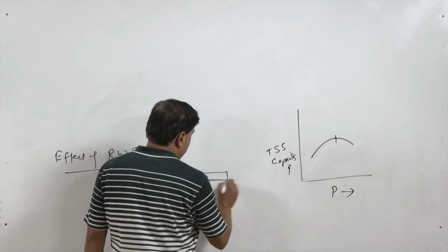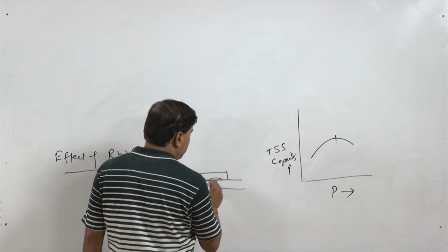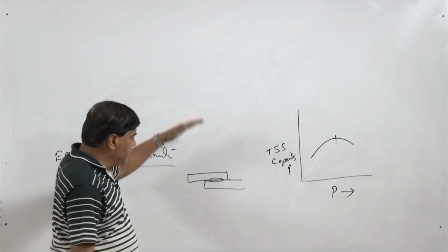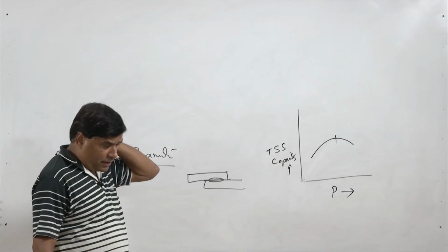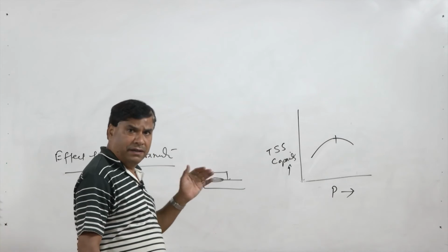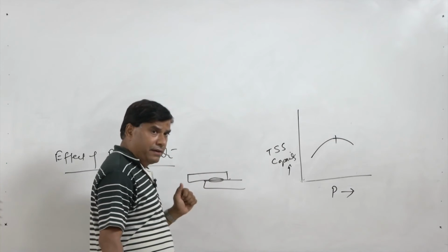If the pressure is too high, then the increased metallic intimacy at the faying surfaces will decrease the contact resistance. So under identical current conditions, the amount of heat being generated will get reduced, and that in turn will reduce the nugget diameter.